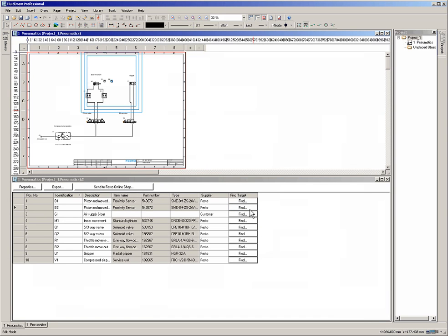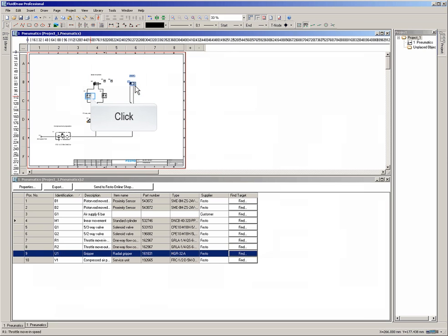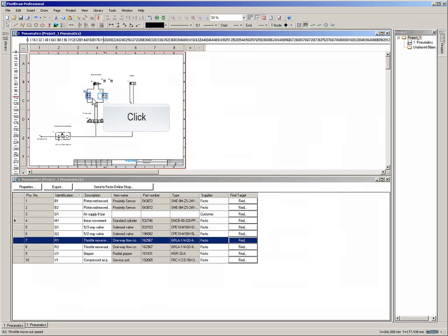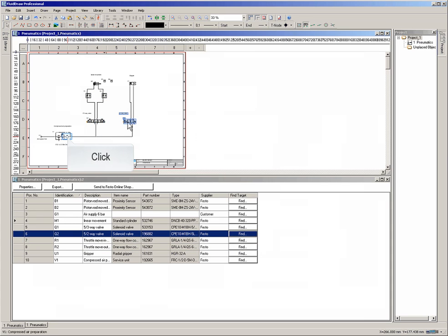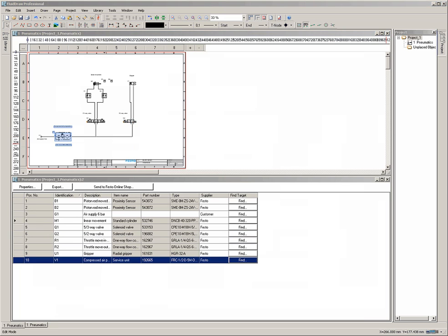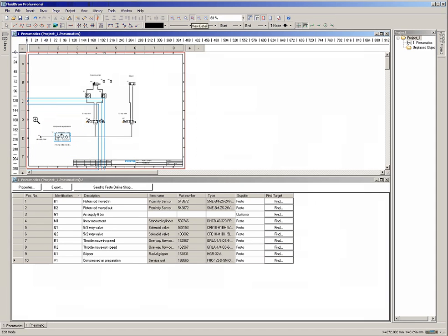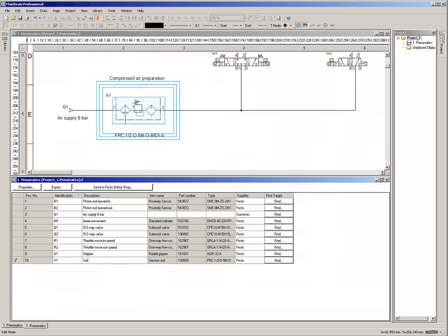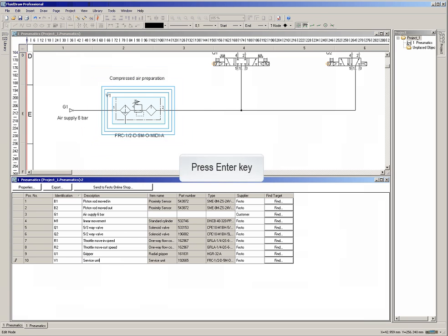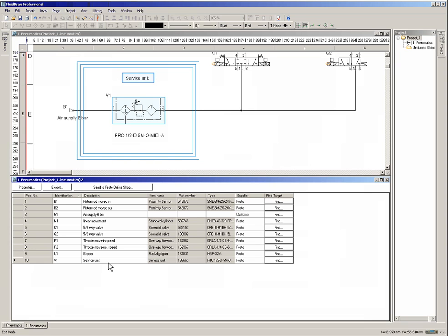The same way a click at a parts list position highlights the corresponding symbol, a click at a symbol highlights the corresponding line in the parts list. Click into a cell with an attribute value to change it. The display text in the scheme will be updated immediately.